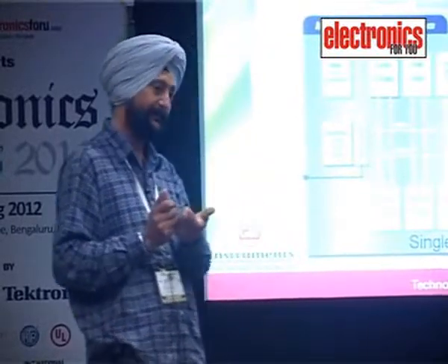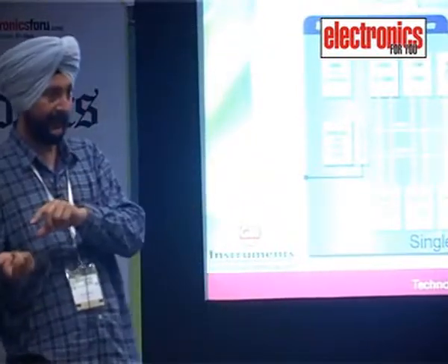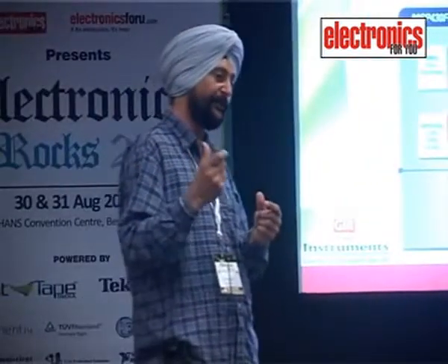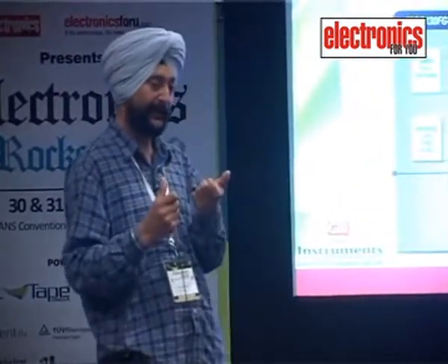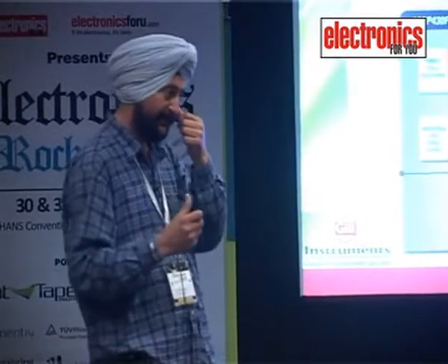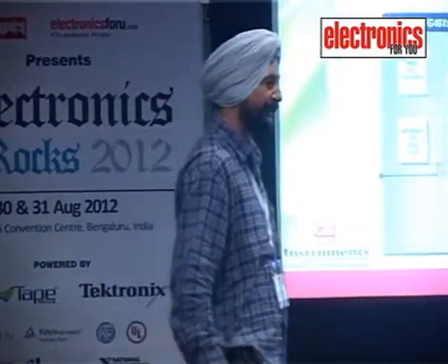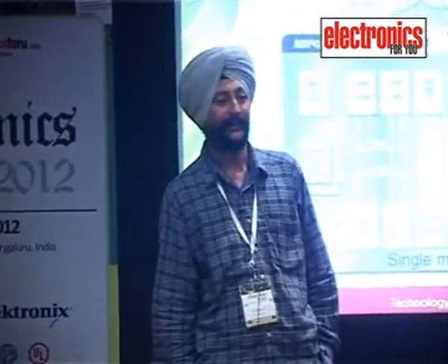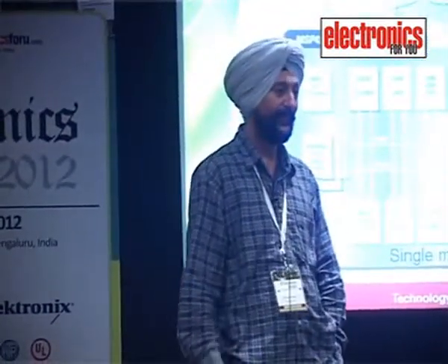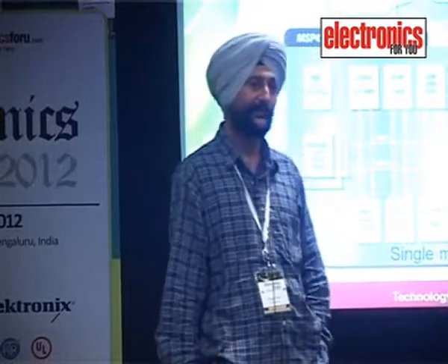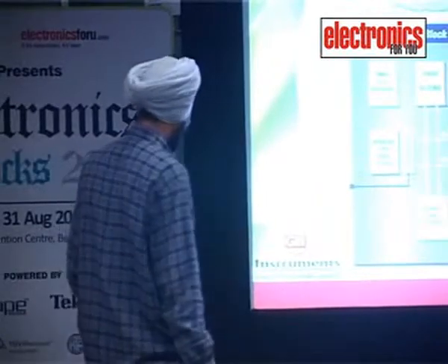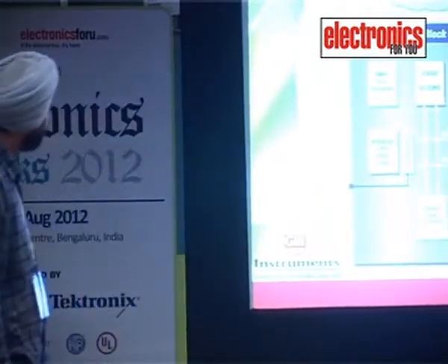It will help you to get some samples from ADC, and then the next DMA channel, it will help you to multiply the coefficients with the samples which we are taking from the ADC, right? So like that, a lot of things can happen in the background while MSP 430 CPU will be in a sleep mode, right? Because we want to save a power, and as you know, the CPU will consume more power and the peripherals are consuming less power, right?